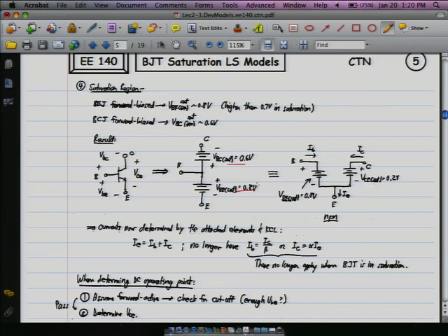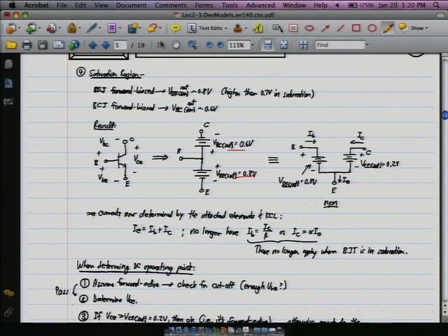All right, so in this case, the current in the circuit is going to be limited by KCL, which just says that the current flowing out of the emitter has to be equal to the current flowing into the base and into the collector. There's that, and then it also says the attached elements, which in general are going to be either resistors or other transistors that are operating in different regions and won't allow that much current to flow.